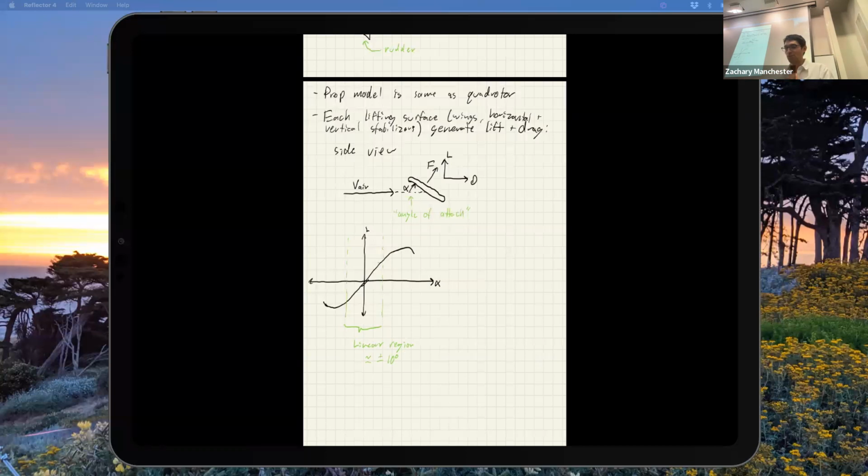Okay, so what do I call the peak over here, where this thing rounds off and starts to go down? Maybe I'll fix this drawing up slightly. Anyone know what that's called? That's stall. When you talk about stall in an airplane, it's the peak of the lift curve where the lift starts to decrease. So I'm getting more and more lift, and at a certain point the lift actually goes the other way. So this peak here is stall.